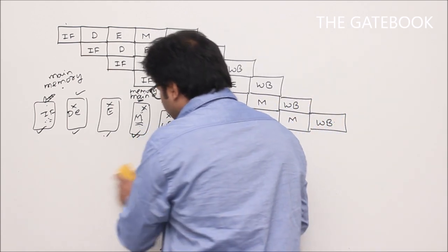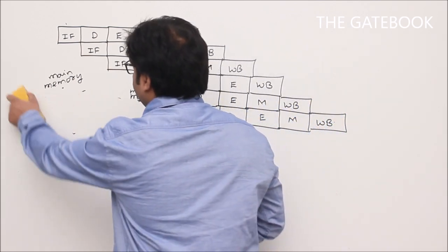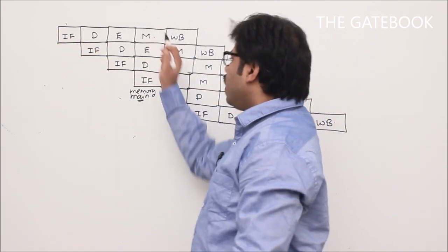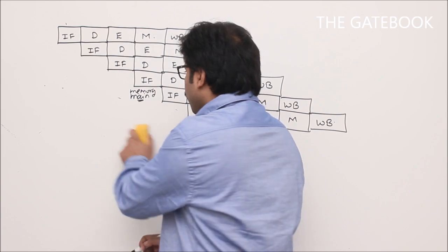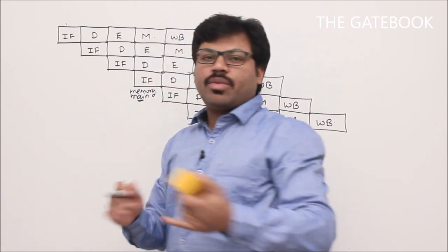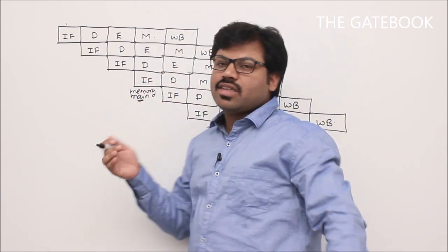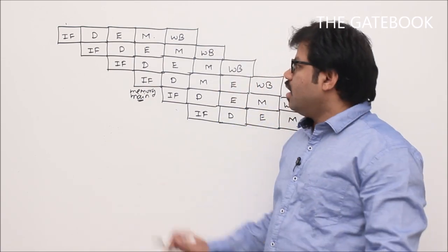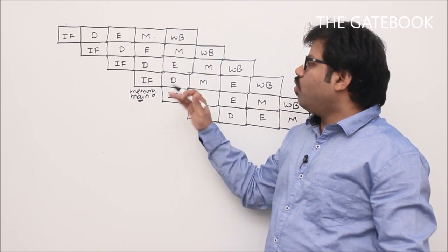So at this moment, you remember, the instruction fetch stage and the memory access stage both require memory. That's why we store instructions in separate memory and data in separate memory, so that they can work independently. Remember it. Now with that situation, you focus.